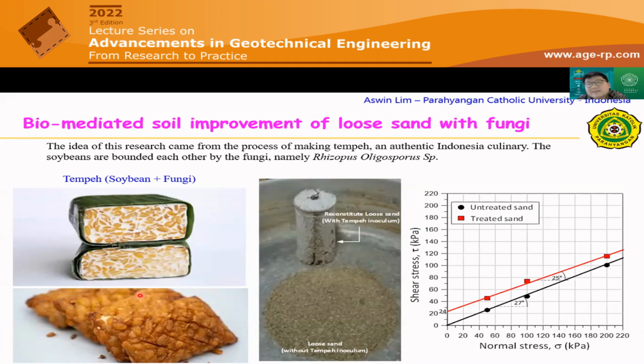Then I tried to mix this fungi, or this tempeh inoculum, into the loose sand and then sprayed it with water content around 5% and cast it in the cylindrical mold, the triaxial cylindrical mold, and then waited for 3 days at room temperature. And when I opened it, we can see that, yes, the fungi has grown entirely covering the soil particles.